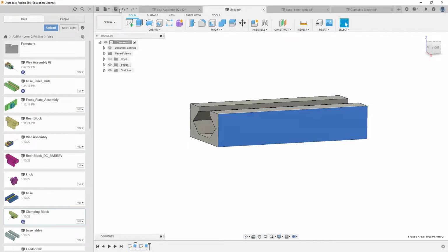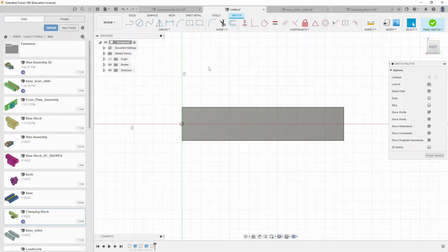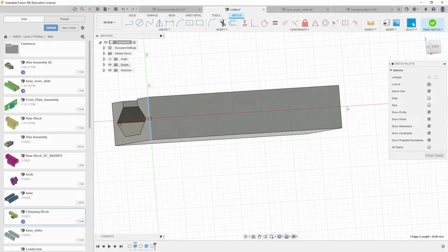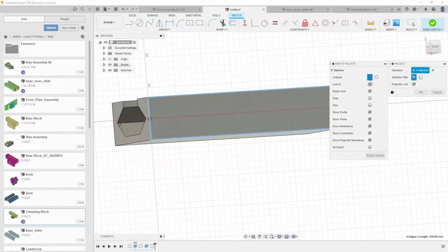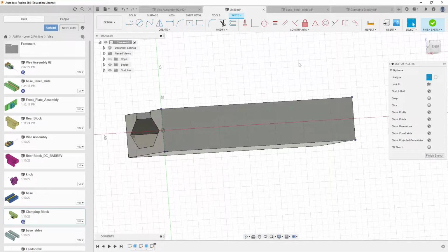We're going to pick the side of this face, go here, and make a centered rectangle. But as you notice, there's nothing really to snap to here. So what I find is easier, if I know that I need to do top, bottom, left, and right, often I don't really know which one I'm going to use, top or bottom, so I just project everything. So I'm picking them, I hit project, they're going to be a construction element, and I click. Okay, I'm going to start going a little bit quicker.